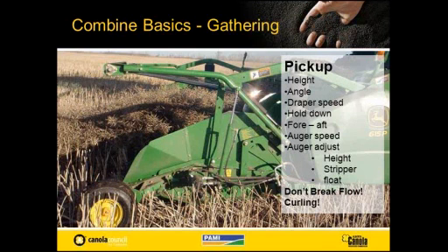A lot of that starts right at the pickup, and most people sort of push it around the field and never pay much attention to it after they've got their initial setup. But in reality, the pickup height is important. That should be adjusted for crops. Obviously, with those that are on the ground, you need to get down there and pick up. But if you've got a well-supported windrow that's sitting up on the stubble, there's no sense combing through right down to the dirt. You can increase that, because that's going to cause, at times, momentary slippage in that, and especially in heavier crops.